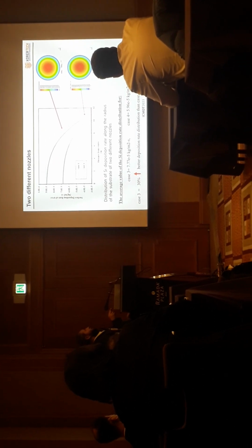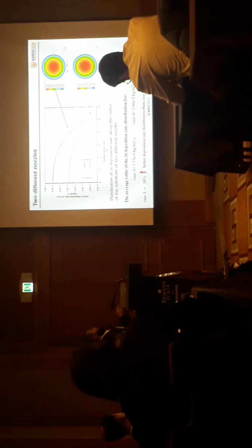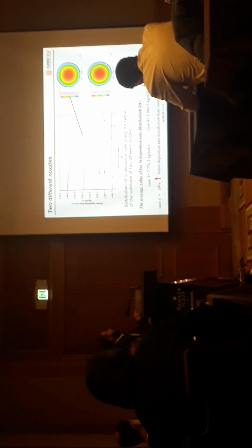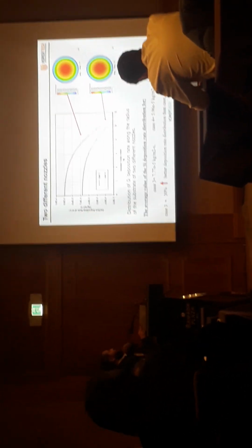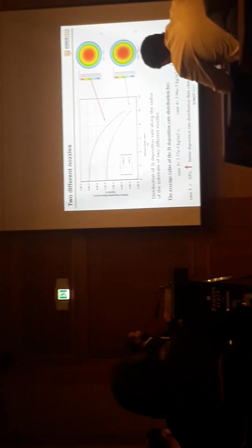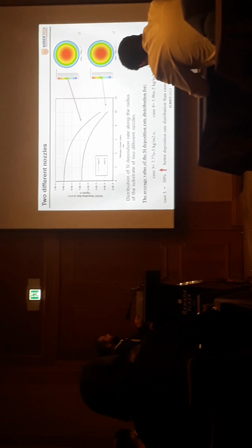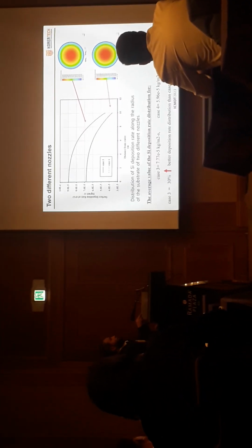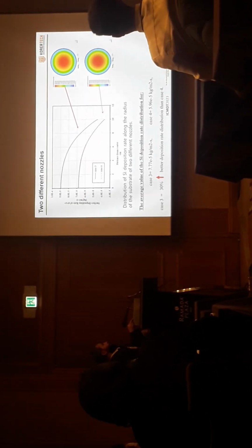And then we kept all the other geometrical and operational parameters the same, and we studied 2 cases. We see case 3 and case 4 for 2 different nozzle designs, and we can see that case number 3 is giving a higher performance, a higher deposition rate, than the other design.